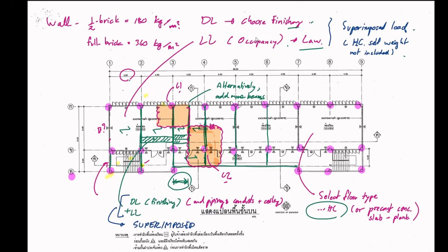From the building act, we have many numbers for the live load. For example, the classroom in a normal school has its own number, and the corridor or the gym is different. Is it practical to choose the greater one so that it is easier for design?